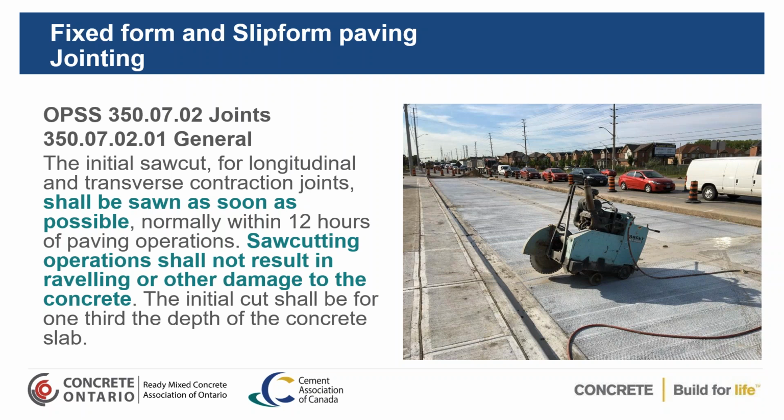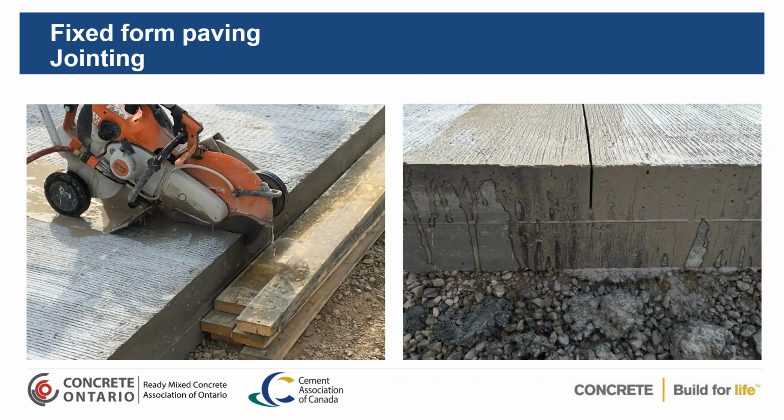Cutting joints, very important because concrete is at its greatest size when it's being placed. As it loses that moisture through evaporation, the concrete will want to shrink. So you'll actually have to cut joints if you don't want random cracking occurring. Usually they're cut within the first 6 to 12 hours, unless you use an early entry saw where you can actually go in within 1 to 2 hours. But you have to look at that type of saw and see if you want to use the early entry saws. They're actually very efficient, and you see those in a lot of jobs now.